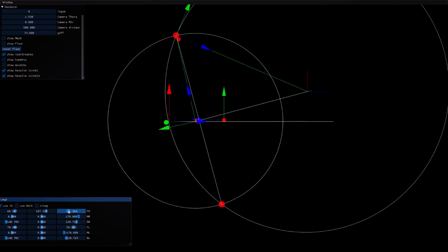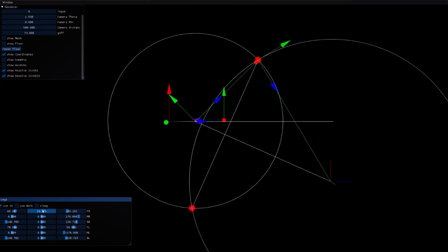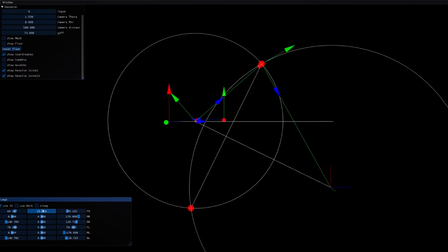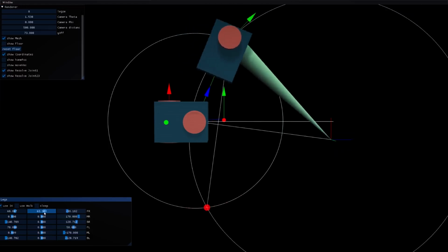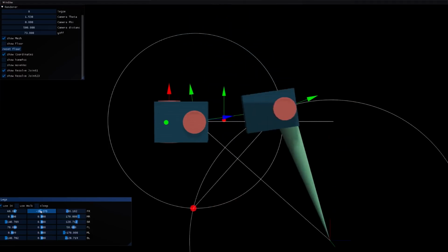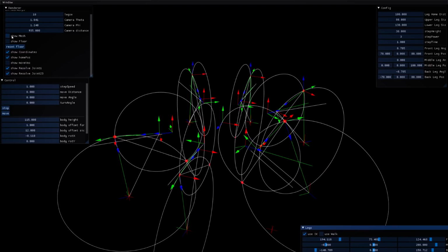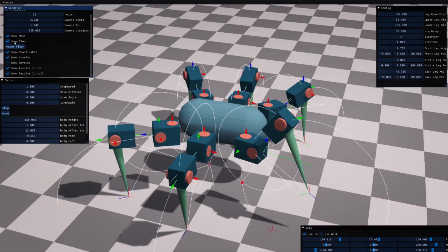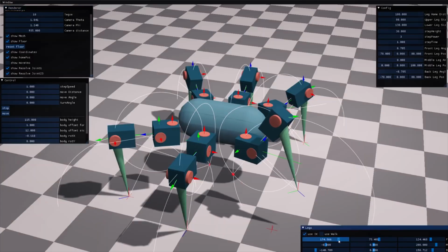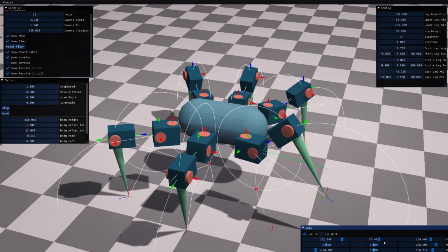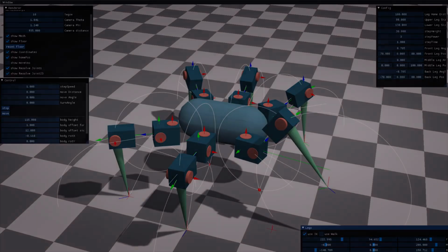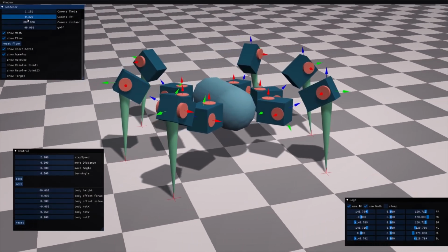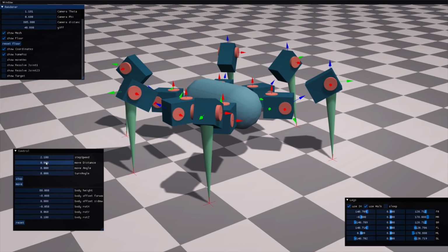Inverse kinematics can look very intimidating to program if you've never done that before, but in the end, it's just about reducing the problem in small, relatively simple 2D problems by rotating and translating your model. You should definitely try it, and making a computer model helps a lot, so you can visualize each step and make sure it's correct. Doing this with a real robot would be a pain, and if you've done it once, you can do it for almost any kind of robot arm with ease.